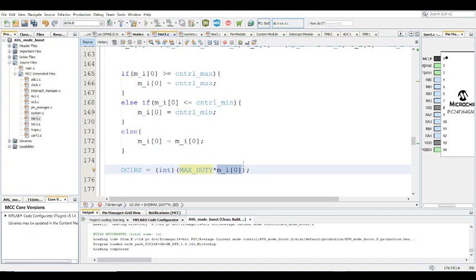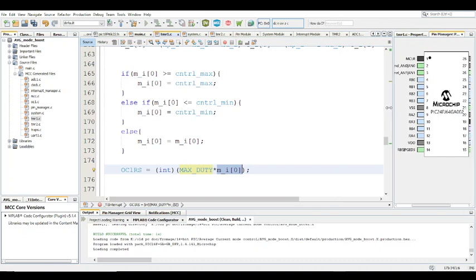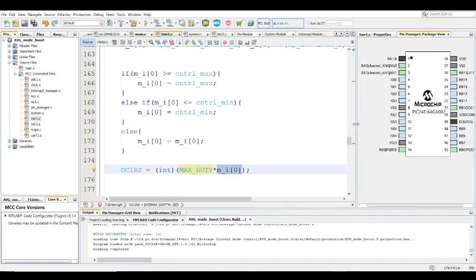You might want to reduce that to 75, 65, whatever, because I don't think converters act very well efficiency-wise at high duty cycles in general. So you want to limit that to something decent, depending on what you calculated, etc. Your theoretical values. But that's essentially what this is.